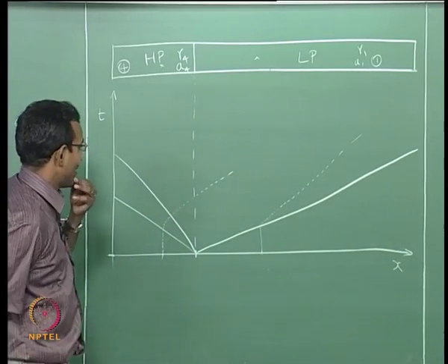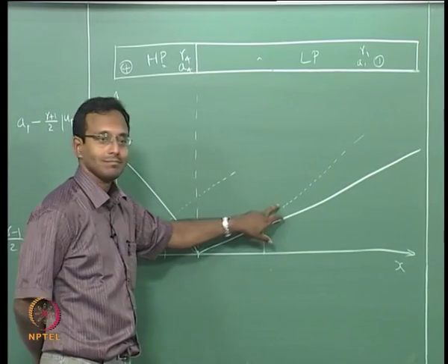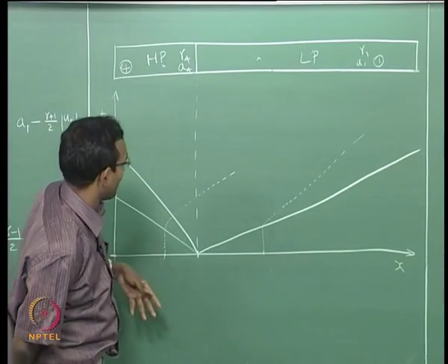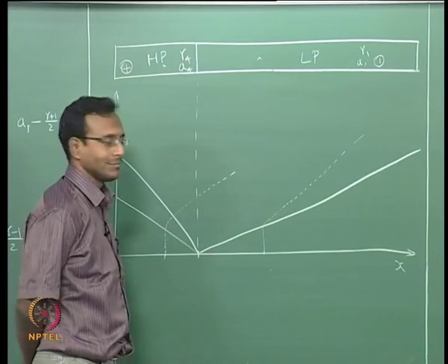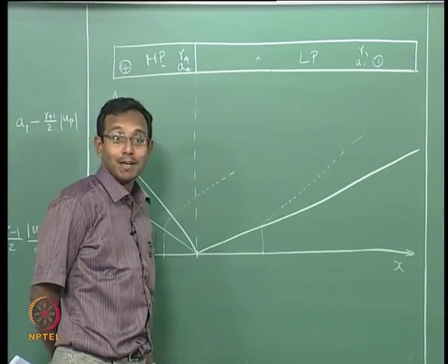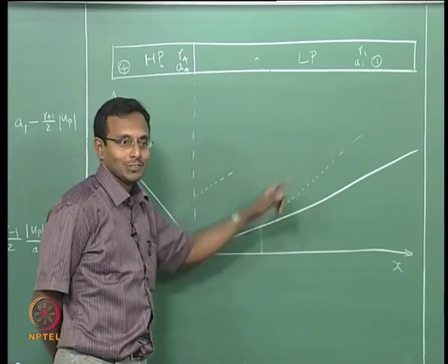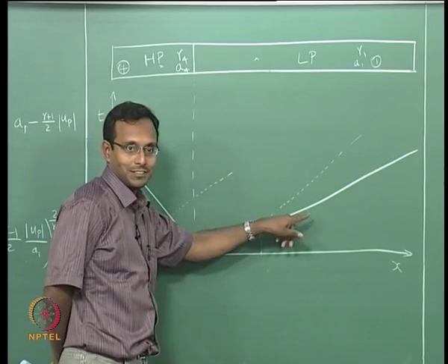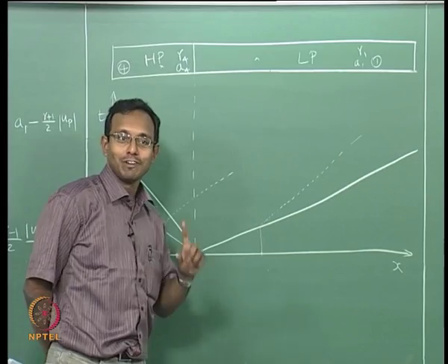Okay. Now I will ask this question: are these two lines parallel? I have drawn it in some way, I do not know whether it is really parallel, it looks like they are not parallel. What will happen if they are not parallel? This fluid element will go and crush the other fluid element. If that happens, what is really happening? This fluid is still pressing on that fluid, so there will be one more extra compression wave created on that fluid, which will go and increase the shock strength till it becomes equal and parallel. That is one way of thinking about it.